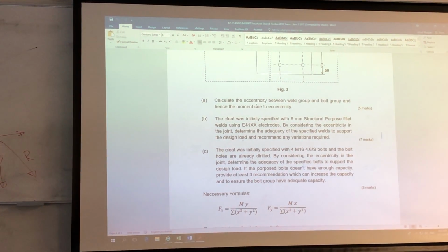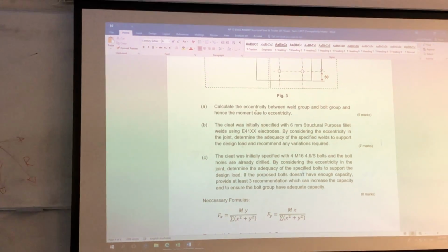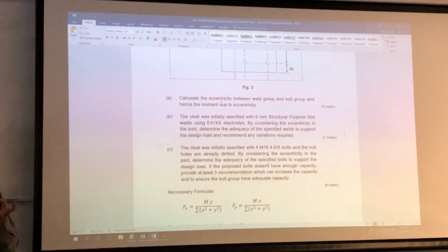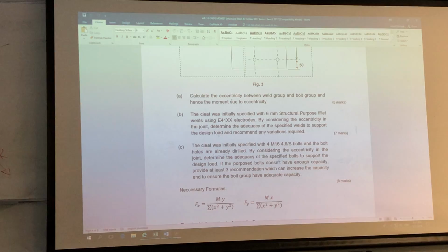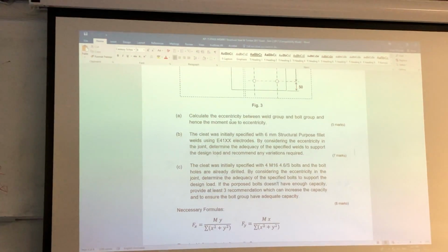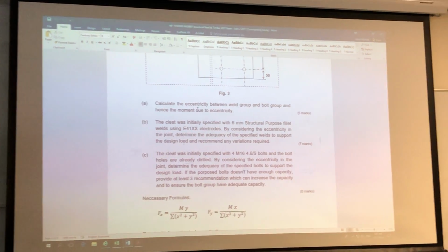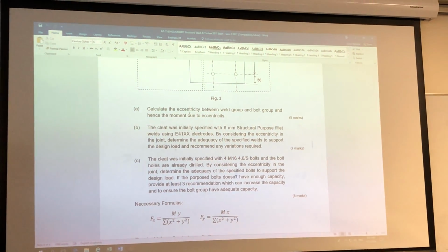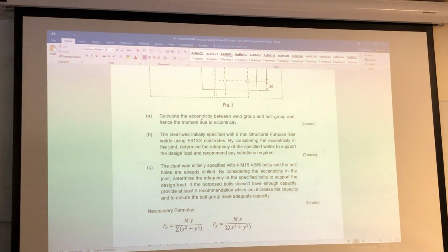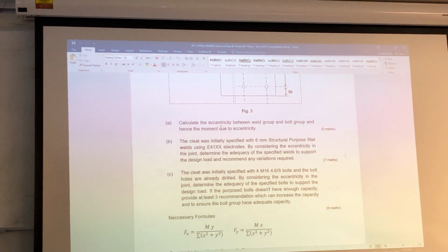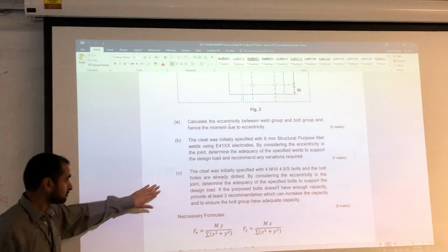It's not easy, right? Especially these things will be done manually inside. Go for smaller bolts, put more bolts, go for high grade, but stick to smaller diameter unless it's really necessary to go for bigger, right? Start with small first.